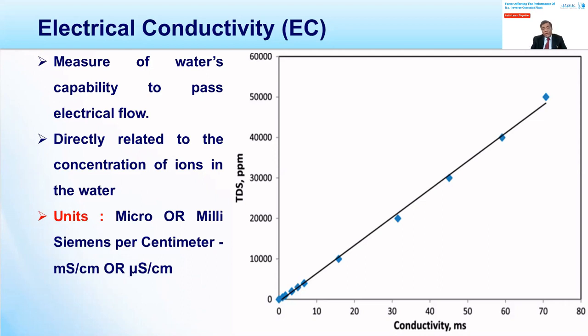In the world, there is no true TDS meter available. All the measuring equipment for TDS is based on conductivity. All they do is change the TDS relationship on the dial, and on the dial indication you receive the ppm. But behind it, the principle is conductivity, and they correlate the conductivity with TDS, and that is displayed on your analog or digital controllers.